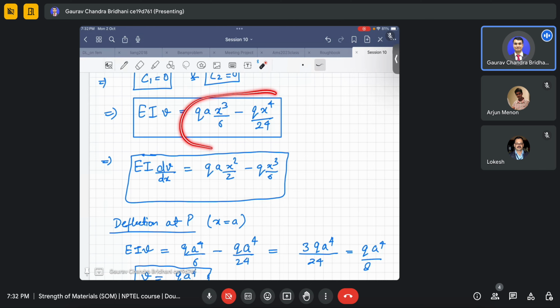So we can even draw it. You can even use an Excel sheet to draw the deflected shape. You can take some value of E, for steel, and I you can take for some I section. If you are exposed to a steel table, you can just take any I section from the steel table. You will have the Iyy, Izz value. So in Excel, you need to put the value of this E and I here.